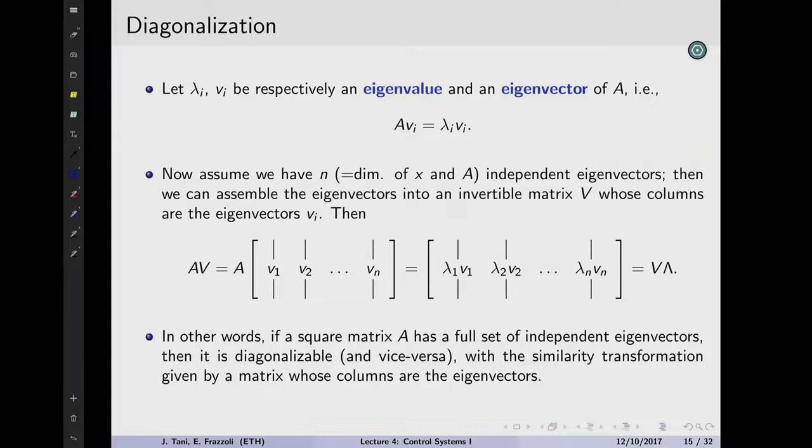So remember, why are we going in this direction? Because we saw that the fundamental properties of the system, such as stability, depend on some structural values of the A matrix, which are the eigenvalues. And the eigenvalues and eigenvectors are defined to satisfy this relationship. Now, basically, if we crank a vector through the A transformation, you can always imagine A is a matrix, but the geometrical interpretation is a linear transformation, no?